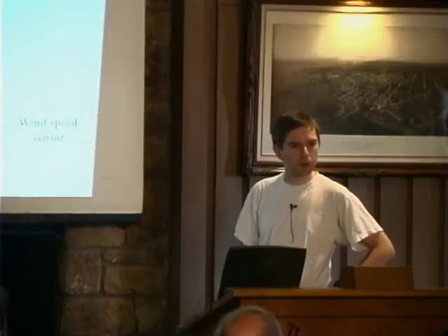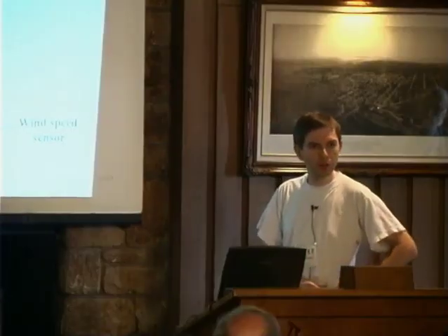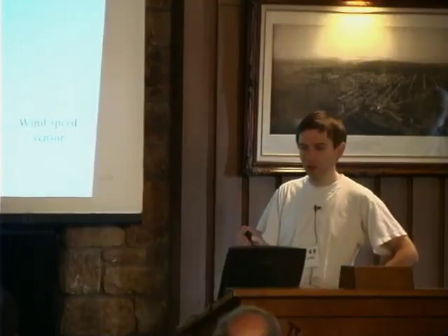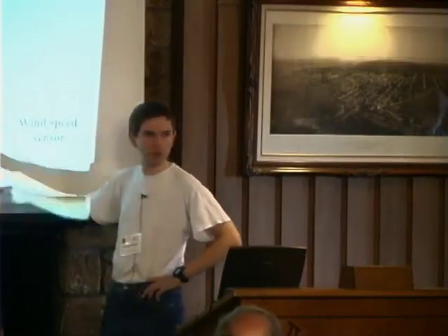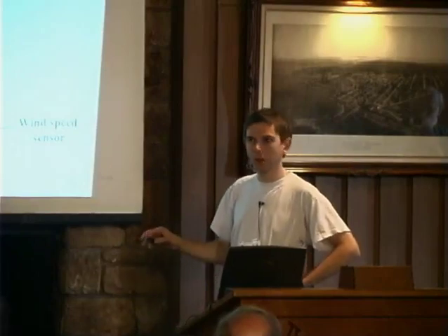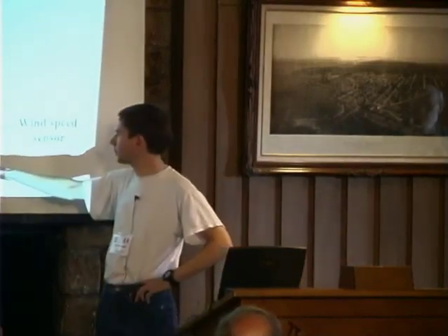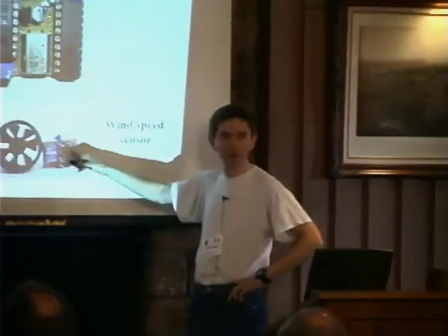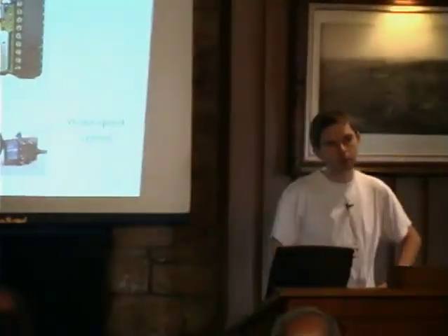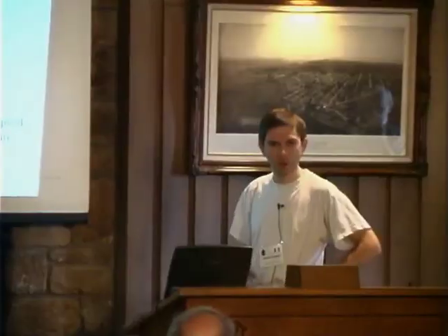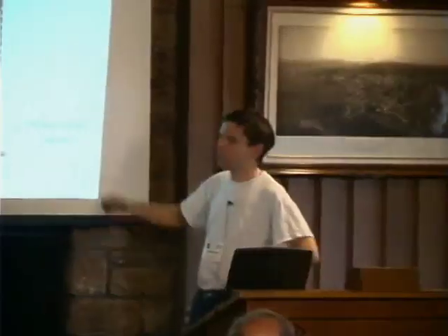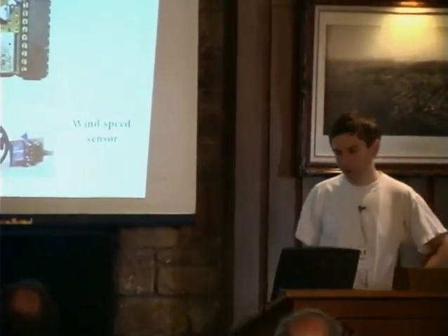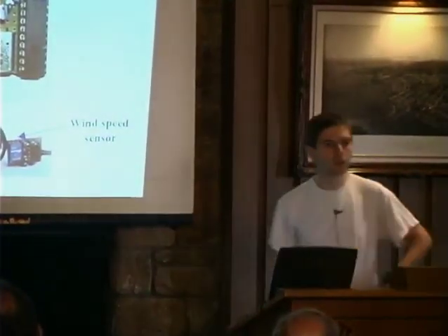So does that use a magnetic reed switch inside in the glass? No. That's electronic. So that's just the magnetic field generated by the sensor, which is amplified by an operational amplifier, and then the result is counted by the microcontroller and converted into wind speed.